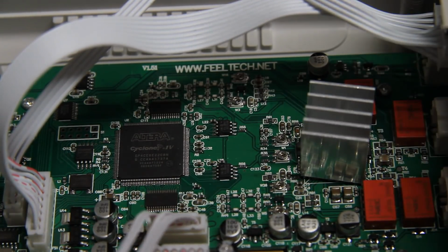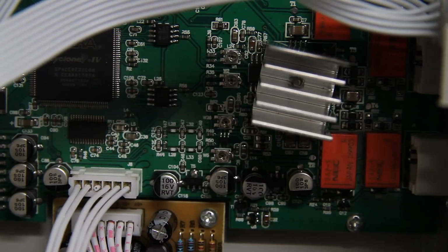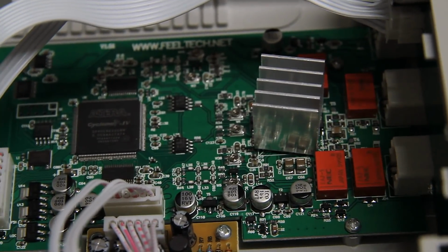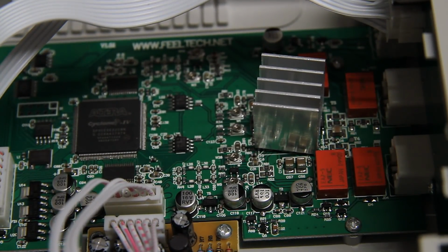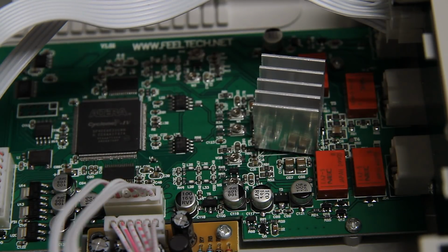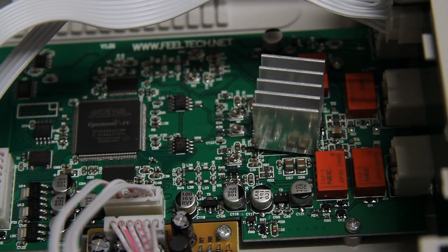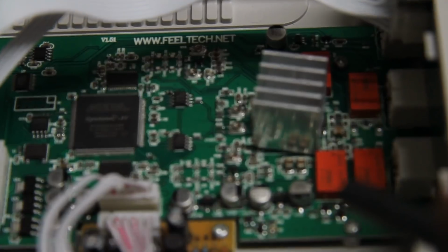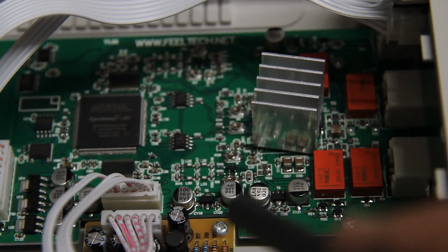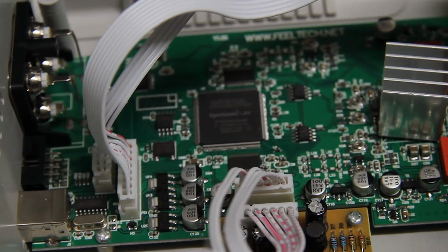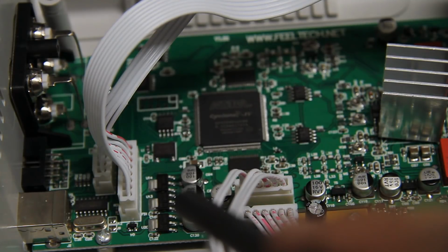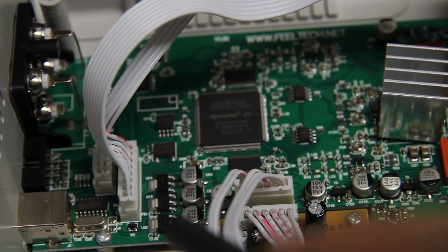Under the heatsink, I don't want to take it off. Maybe I break something in this process, even though it's screwed in the middle. There are just op-amps from Japan Radio Corp, JRC, maybe 455D, not quite sure. Op-amps under there, and there are some NEC relays around. For powering the FPGA, we got a 3.3 volt regulator, a 1.2 volt and a 2.5 volt regulator.